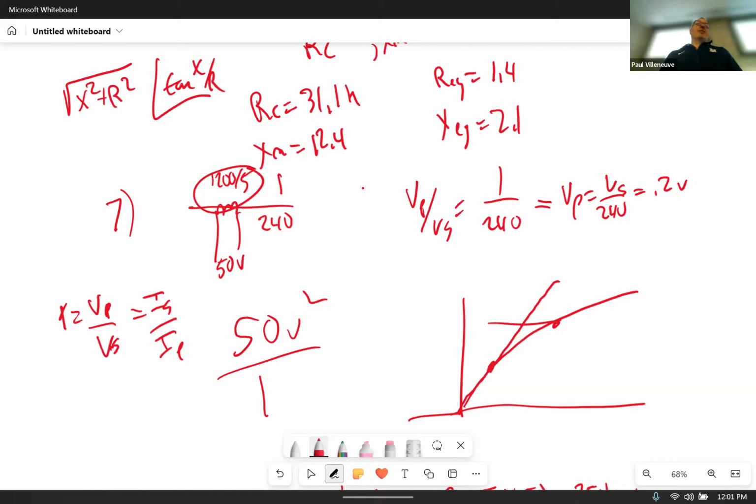Yeah. Well, the question is, why did you think you did them wrong in the first place? Why did I think that? And then later on, one of the other questions, the way I read it, got me thinking about phase versus line, and I realized that I had the wrong voltages and whatnot. It's some funky stuff. Yeah. Draw a picture. If you're stuck, look at phase and look at line and a delta or y, and then it starts to get obvious for you.